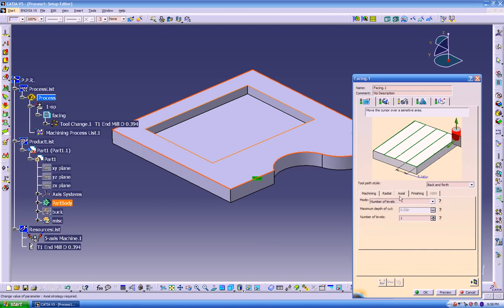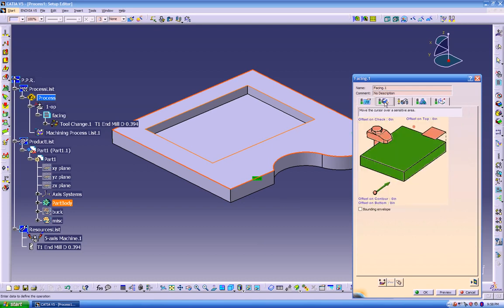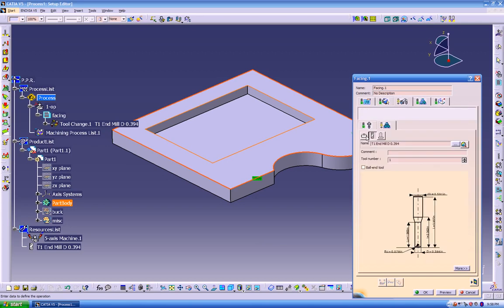It's 50%. It's going to ask you how many passes you want, the levels you want, and if you have any finishing passes, finish at the bottom, and it's going to ask us for the thickness over here. It's pretty self-explanatory, but right now we just make one simple pass before we make it too complicated. Over here you can put the offset. Instead of coming to the bottom, you can stay above, and you just choose the option over here.